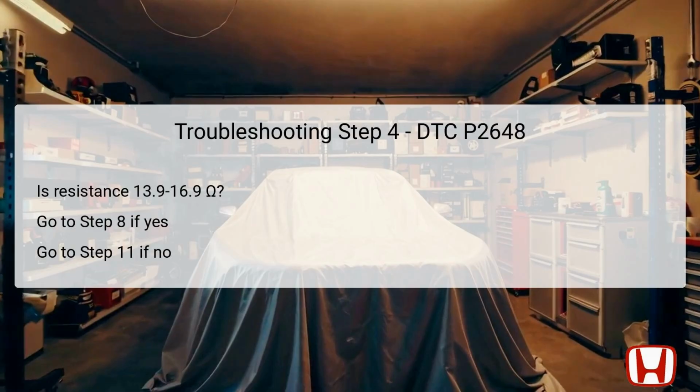Conversely, if the resistance readings fall outside this specified range, you should move forward to Step 11, which will involve diagnosing potential solenoid failure or wire integrity issues. Understanding the resistance helps pinpoint where the fault lies, whether it's in the solenoid or in the connectivity to the